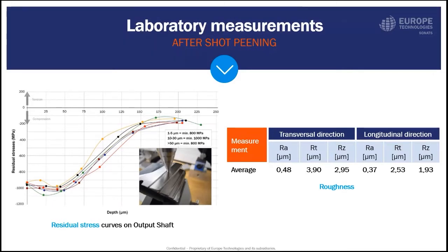X-ray diffraction is a non-destructive testing procedure that uses X-rays to determine the lattice spacing in the material at and just beneath the surface. To determine the residual stress profile within a material, the surface is electrically polished, so destructive, a few microns at a time, and XRD measurements are taken.